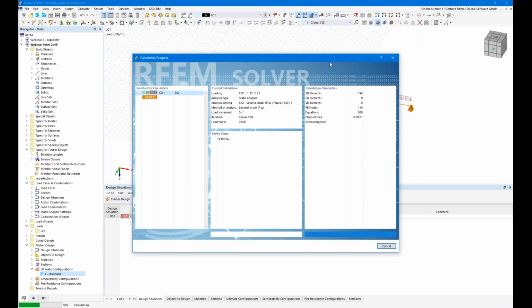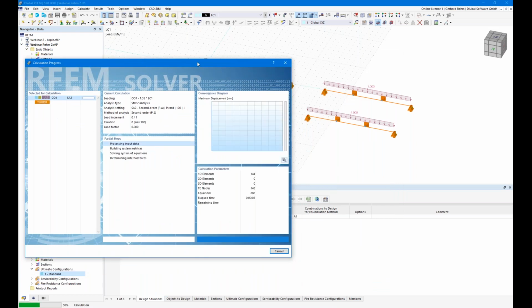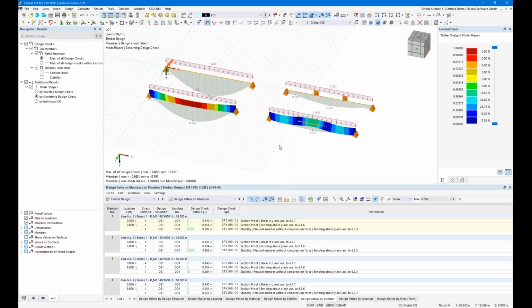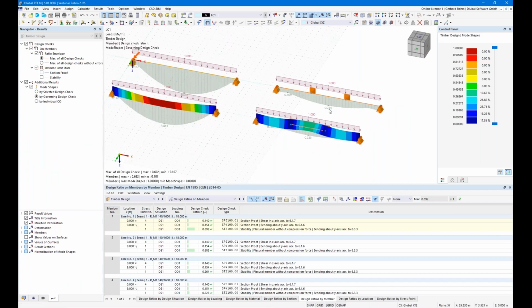and then we can check the results. Of course, the ratio needs to be or must be smaller now than the ratio from the left side. Okay, so yeah, the ratio goes down to 26 by the analytical solution, and the eigenvalue method here. Yeah, the difference is a bit more now compared to the left side, of course, because this assumption that there's a constant moment distribution is of course not completely true, because it's not really constant. Yeah, and that's of course there's a difference.